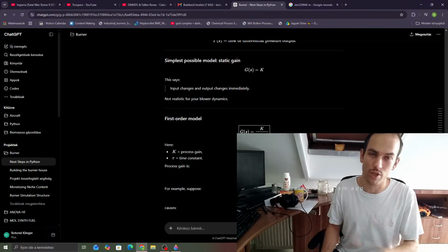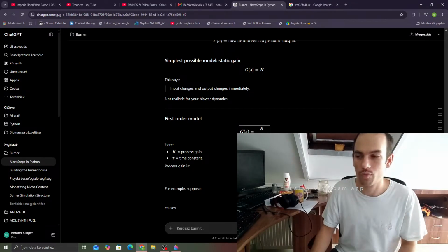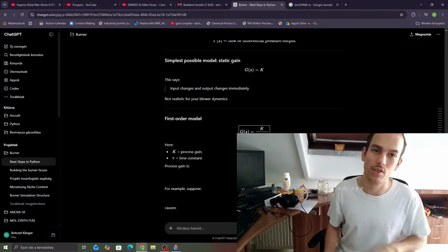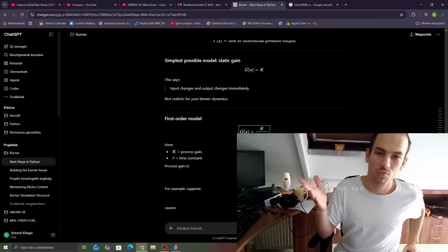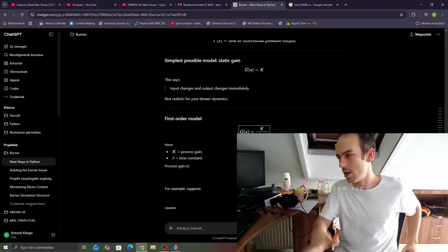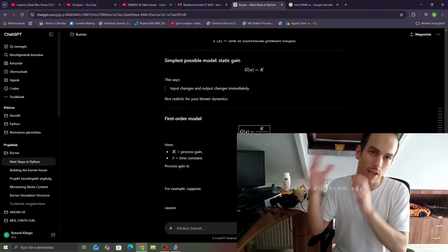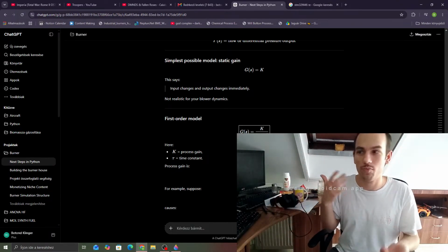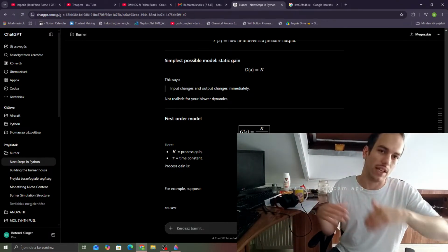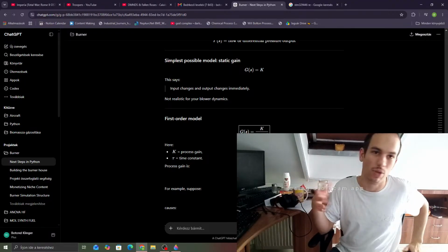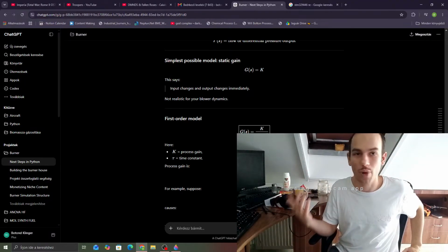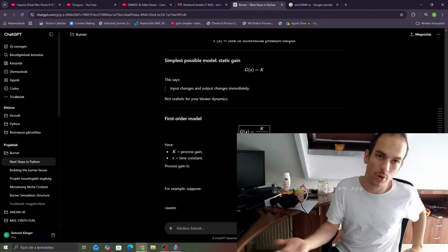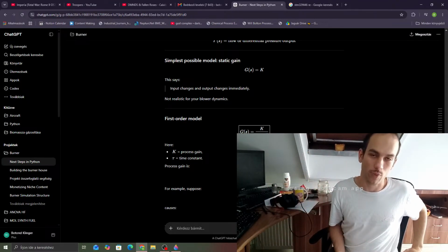That's why it is important to set the excess air and all this kind of stuff accordingly. There are emission considerations as well, but the point is that you need to adjust in time, within about 10%, for the little fluctuations, because pressure change can happen, or temperature change can happen, and we want to control that as well.